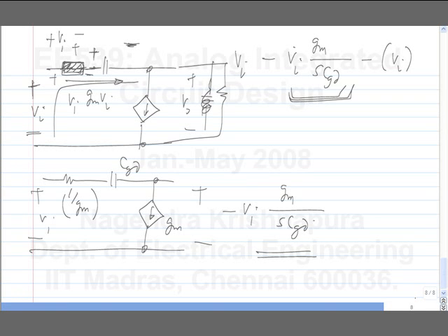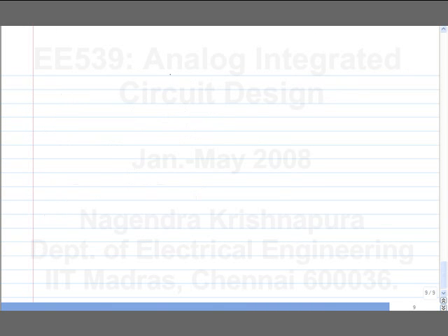The current through the capacitor, the current through the transconductor depends on? Yeah, so that is actually a good point, that if this is the intrinsic CGD of the transistor, the whole thing doesn't work, right? If it's only some additional capacitance that I've added, it will work. Because see, if I have a transistor, it has some CGD, and I can't remove the CGD or lift one of its terminals or anything like that. But if I have a capacitor that is deliberately added across the device, then the zero because of that can be got rid of by having a resistor.